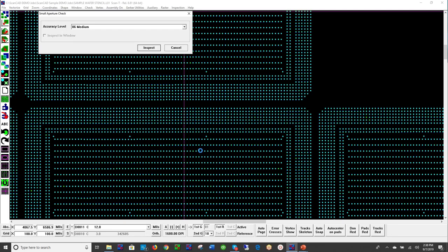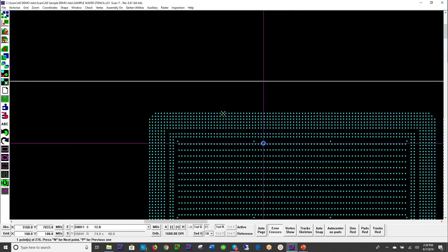I should share with you that we have customers in the textile industry that are inspecting dies that are used to extrude high temperature, high pressure polymers that make threads. And they are using hole diameters of 0.006 to 0.009 of an inch. And they literally have hundreds of thousands and sometimes millions of apertures in a die. The same system that inspects a wafer stencil for semiconductor will inspect that die for the textile industry, or for oil and gas, or for medical, etc.